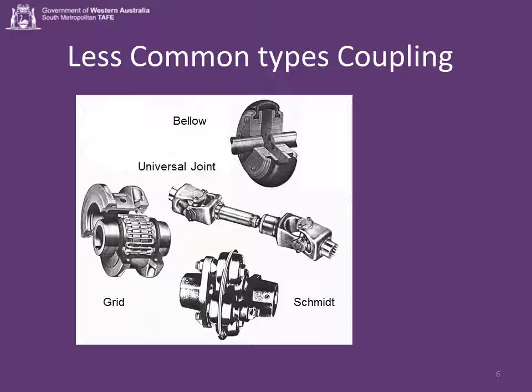The main disadvantage of the system is you generally need special motors. Remembering that an electric motor will try and start at its running speed, so basically it'll go from 0 to 1500 or 3000 RPM as quick as possible, in a few tenths of a second.